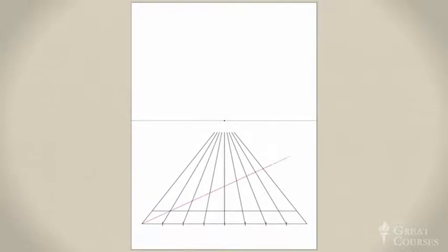We draw a diagonal, very light and thin, through the opposite corners of one of the bottom foreshortened squares. We carry that diagonal across our receding lines. Actually, it's better not to draw the whole line. I've done it to make the example clearer, but you could just make small marks on each receding line where the diagonal would traverse it. It saves some erasing. At each traverse, draw a horizontal. Make the lines lighter and thinner as you recede.